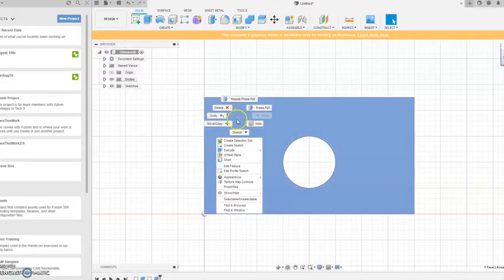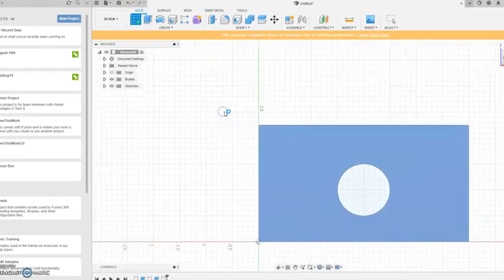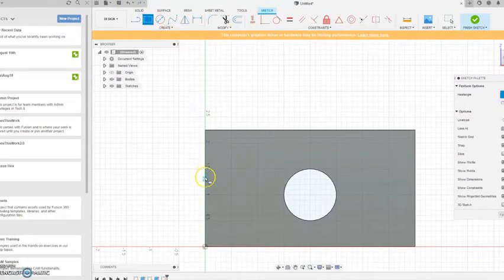I can right click, create a sketch, or I can come up to the toolbar, click on that. There we go. Up top, this toolbar is called a ribbon. I know it needs to connect here. I know it needs to be 1/2 inch by 1/4 inch. Remember, I can hit tab on the keyboard to go between the two, because if I try and click, it's going to move on me.